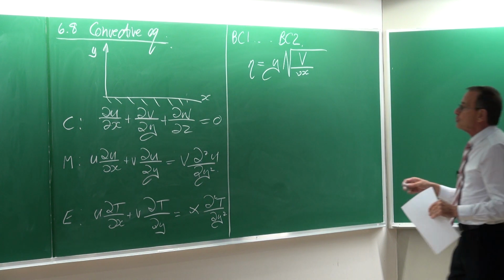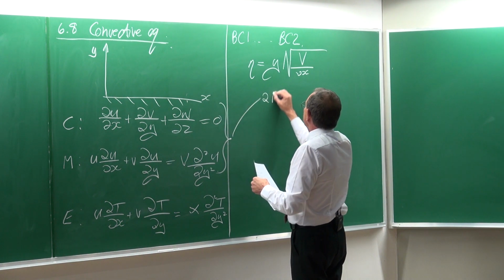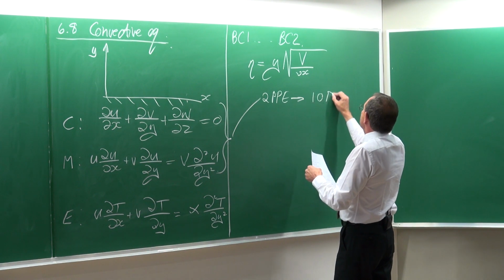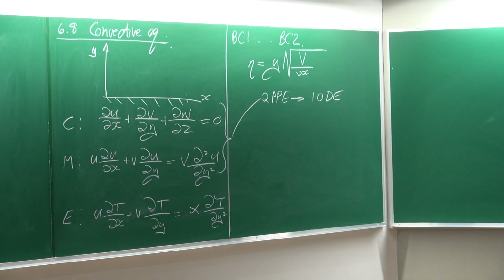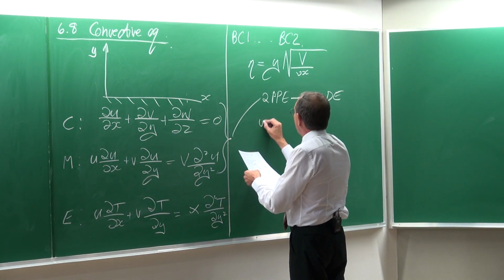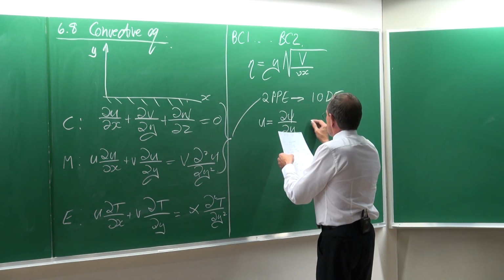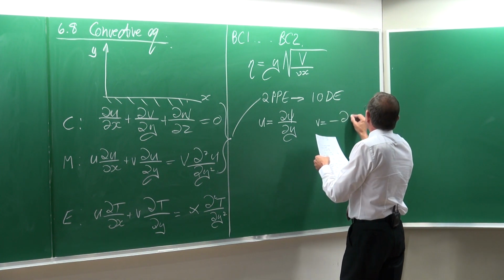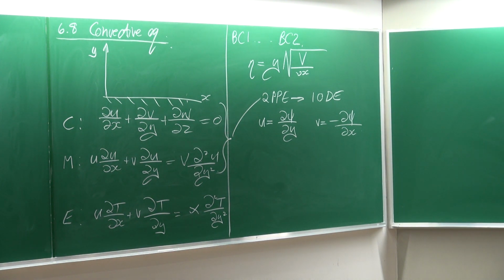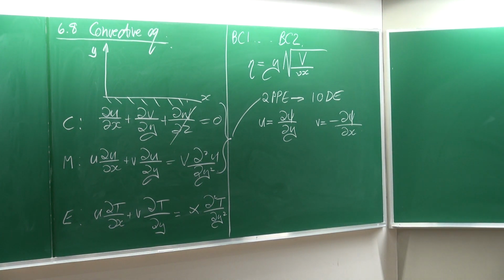And by doing it, he could actually take these two partial differential equations, two PDEs, and he then generates one ordinary differential equation from it. And that is being done by using so-called stream functions, which you've done in fluid mechanics. Those are the stream functions for the u velocity and the v velocity. Of course, he made the assumption there's no flow in the z direction.